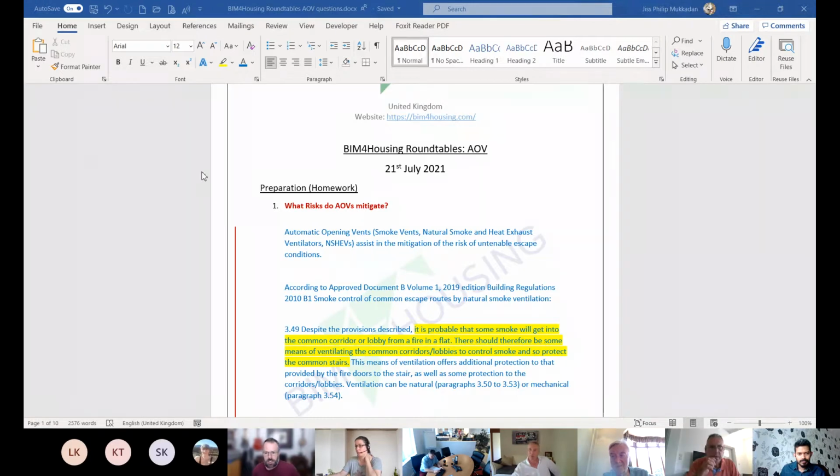I think a few things we commonly see is the actuators not fixed particularly well to openers. Openers that strike elements of the building as it opens, so they don't actually open to an effective clear area. Along with this issue of combustible items being left in essentially an area which should be sterile in a residential setting.